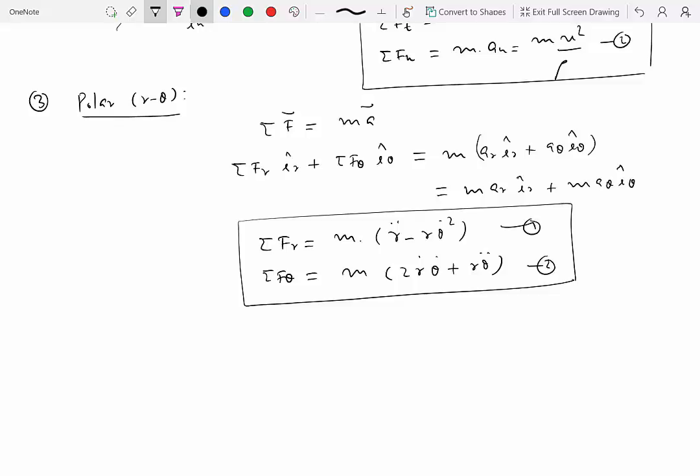In statics class, the right-hand side was almost always zero because there was no acceleration, there was no movement, but that is a temptation that you would have to resist from this point onward, where you make the right-hand side equal to zero. So unless you can confirm that acceleration is zero, please don't try sigma F equal to zero in any case.